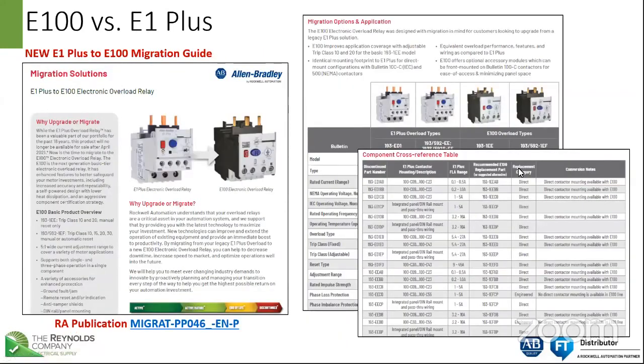With that being said, there is a really good migration document that Rockwell has already published. If you don't have that, please let us or your salesperson know, and we'll make sure you get a copy of that. The migration guide does a good job of explaining why the migration to the newest one, and it has a component cross-reference table at the back end of it. So you can take a look at any of the current part numbers that you have with an E1 Plus, and it'll tell you what contactor it was mounted to, provides you the full load amp range, and then the recommended replacement part.